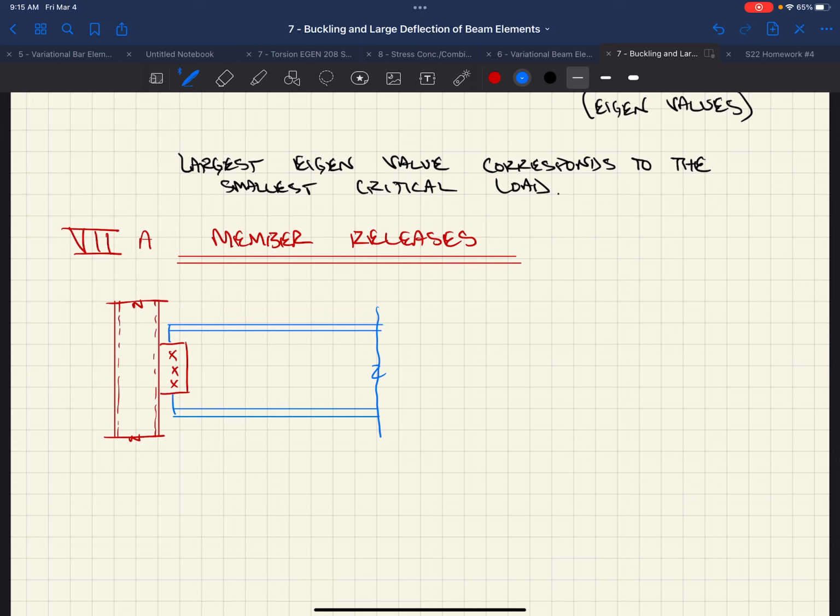What do you mean you can't over design? There's requirements on the thickness of the plate versus the. Can't you just bump it up in the table? Yeah, but those table values, if you look in the steel manual, underneath the shear tab, it goes through all the connections, right? Well, there are some inequalities that the shear tab needs to meet with respect to thickness of the plate and weld sizes. Same with a single angle connection, they assume that the angle can kind of pull away from the face of this column or supporting member to allow some of those rotations.